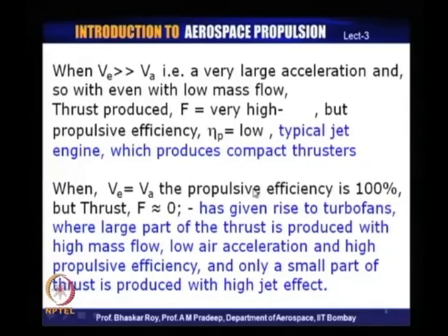Now, this is obviously a very desirable phenomenon, where your fuel efficiency is going to be quite good, and this is the kind of engine that normally we can see in propellers. When we operate with propellers, propellers typically operate with low acceleration, operate with very high mass flow, and operate with very high propulsive efficiency.